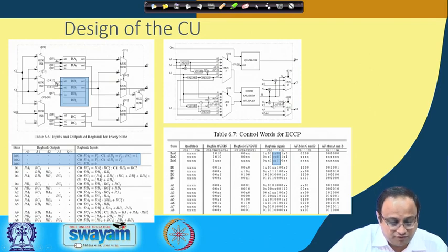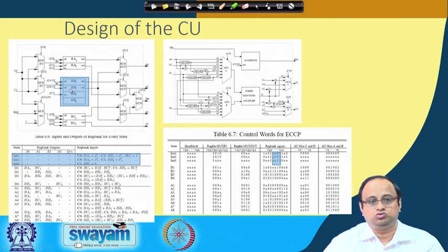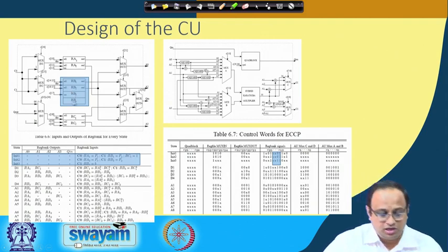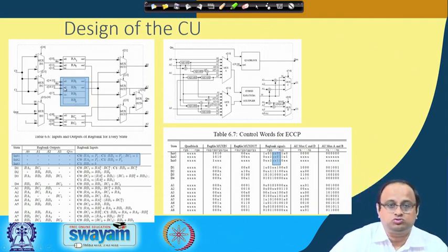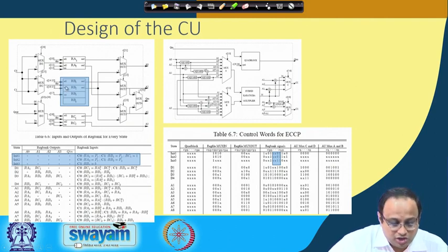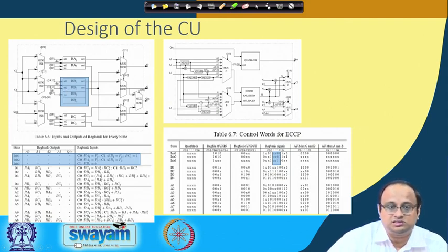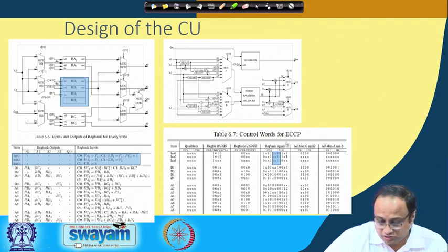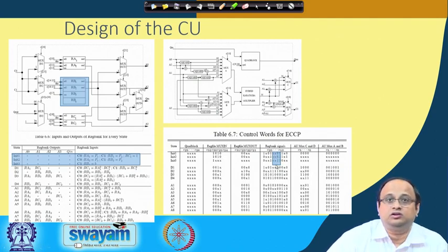Now if you see the logic here, when you want to write into RB1, as I said, the first address, address 1, is used to choose the write address, and address 2 is used to choose the read address. Address 1 is essentially controlled by C14 and C13, and the read address is controlled by C16 and C15. That is shown here by this small thing.